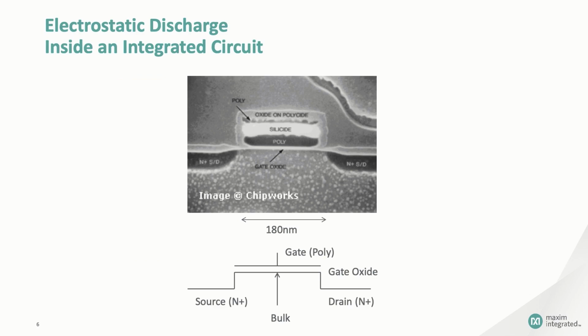And to understand why, we need to think about the structure of a MOS transistor. A MOS transistor consists of a channel that can be either conducting or non-conducting. The state of the channel is controlled by a gate electrode that is electrically isolated from the channel by a thin layer of silicon dioxide. The electric field caused by the potential of the gate relative to the potential of the channel controls the flow of current in the channel.